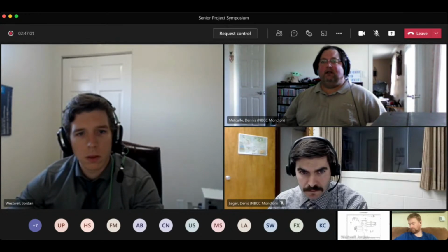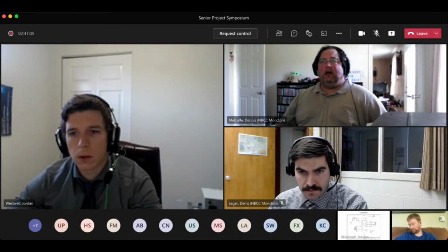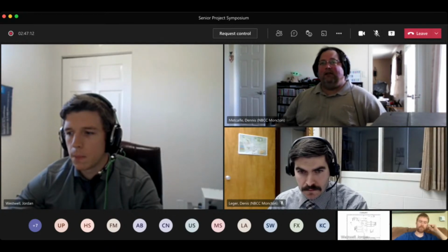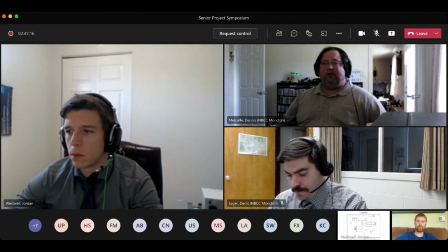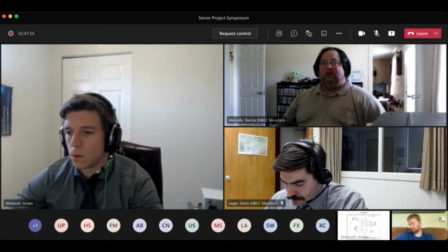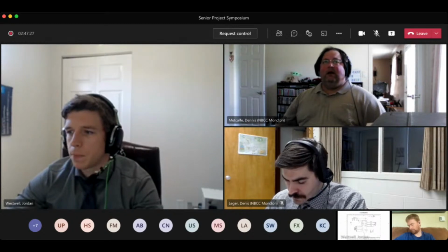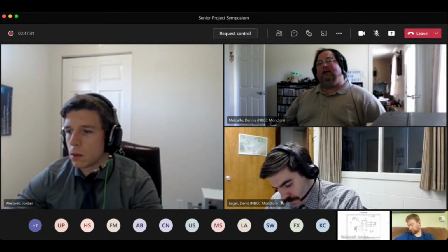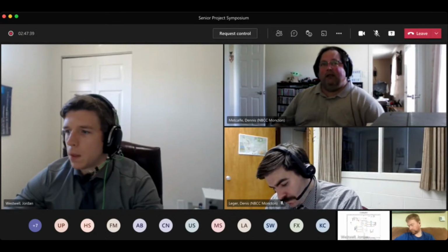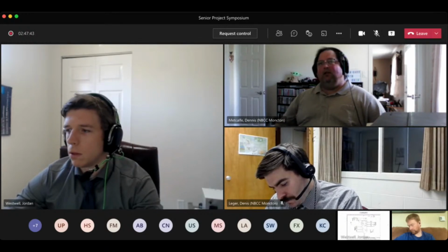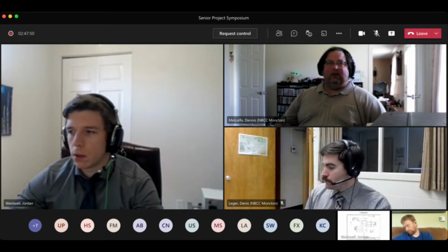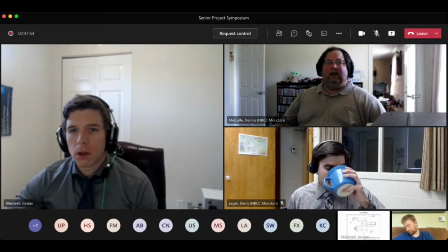Do you understand what I mean? For example, where the LEDs are, you don't show me how the LEDs should be connected, or how the servo. You have these pin values, but you don't identify where they go to symbolically, or in the case of the servo, maybe what the pin values on the servo itself are. I understand that if this was a schematic to do schematic capture for your PCB board, it definitely works well. But as a documentation schematic, which is kind of what it is here, it makes it very difficult for me to follow through. I just found that a little bit rough in that case.